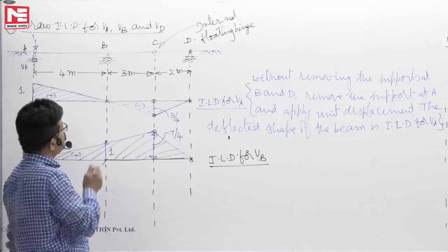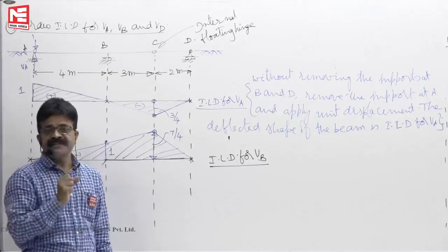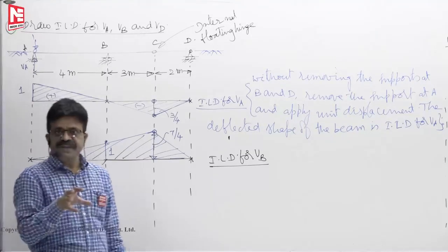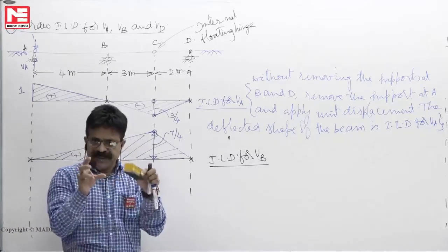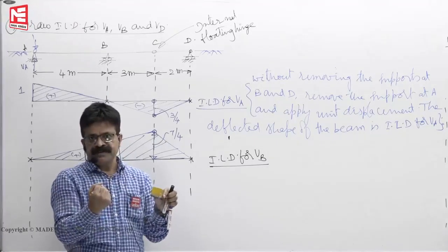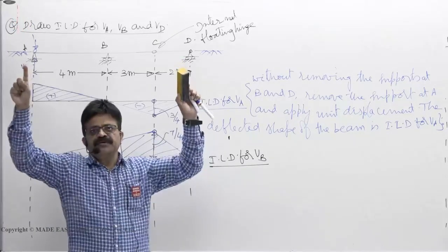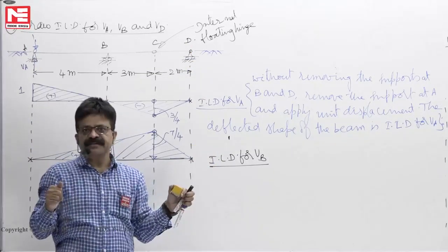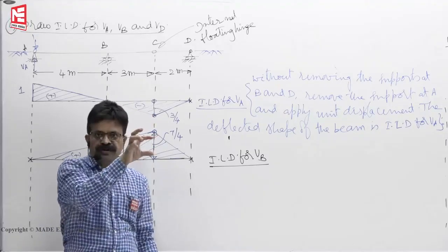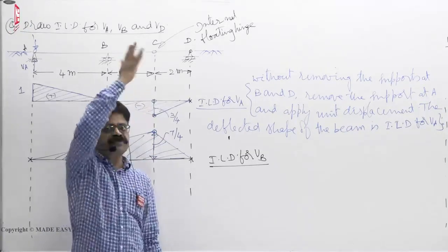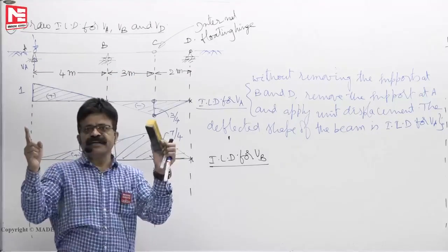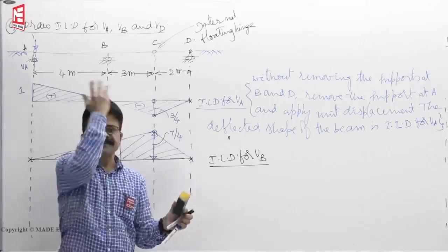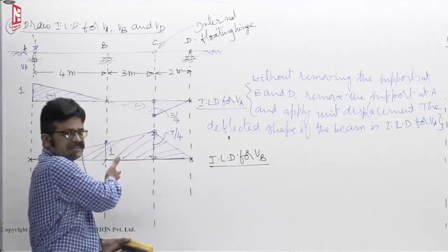Okay. In steel also, you will get such type of things. Prying actions are there. In design of steel structures, again I will explain, there we learn prying actions. That is prying action when you are pulling a member. Then the overhangs will try to go up, but if the supporting plate pushes them down, then what will happen? The bolt load, if you apply 10 kilonewton, 2 bolts are there, each bolt is supposed to take 5. Instead of 5, they will take 7 kilonewton because of the same reason.